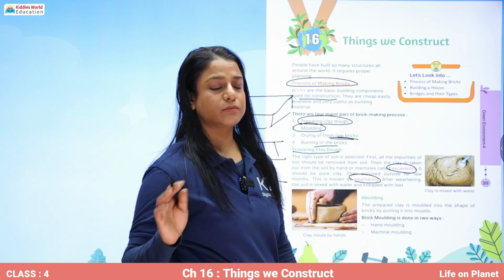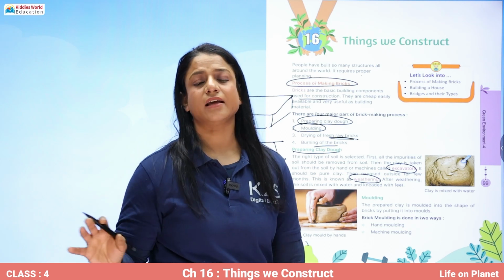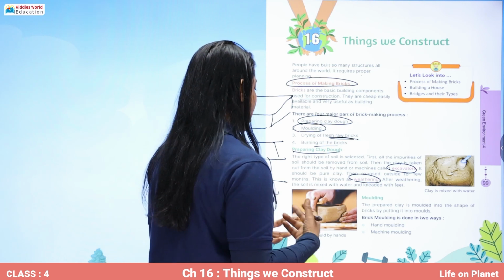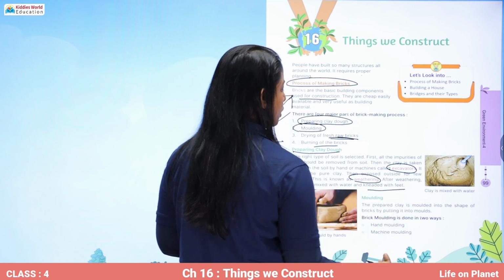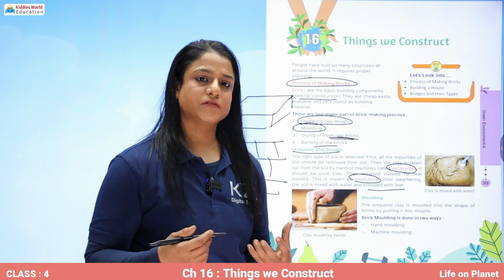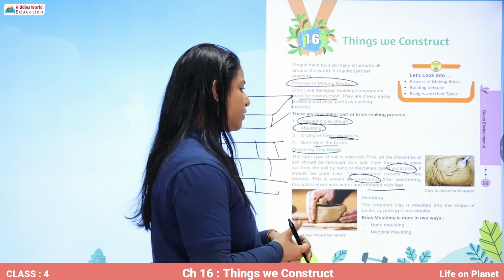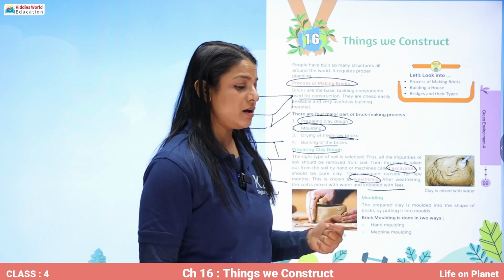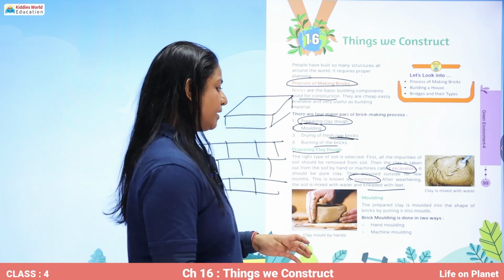Then this clay is being exposed for a few months to see whether this clay can withstand the harsh weather or not. After weathering, soil is mixed with water and kneaded with feet. So after this clay has been exposed to various kinds of weather outside, the soil is being mixed with water, and through our feet the soil is being kneaded.